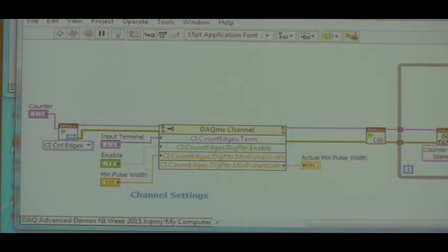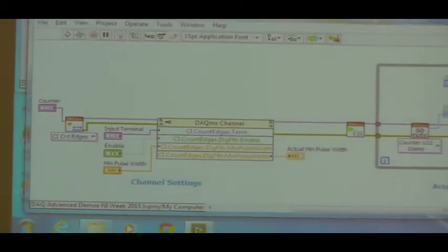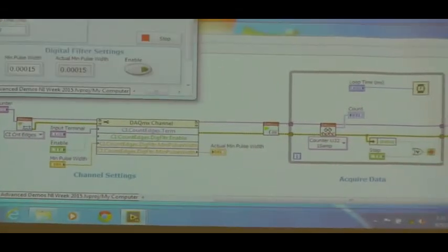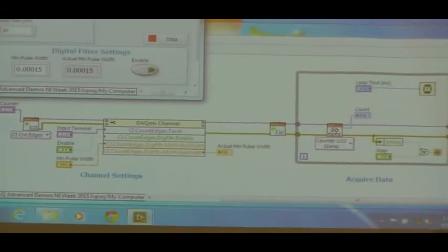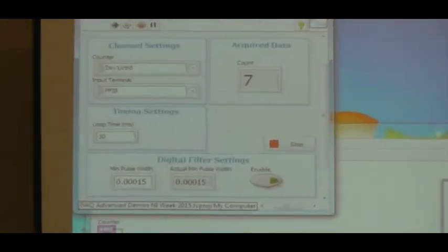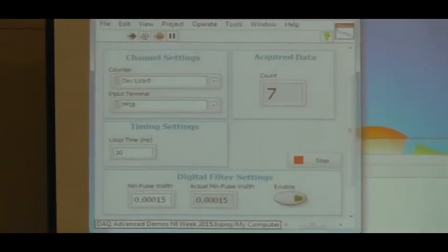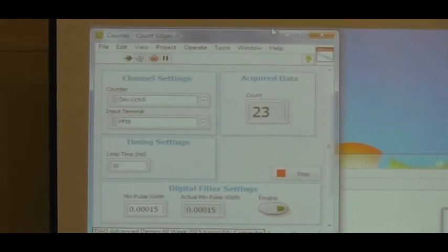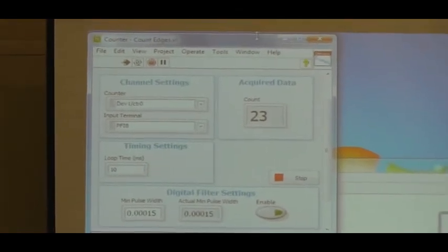So I've just got a joystick here with a big red button on it. I've got it wired up to PFI 8. So when I start my task, if I depress the button, I didn't exactly get one count, did I? What's really fun is when I let go of the button, it usually bounces again. So I definitely don't want to count when the button gets released.